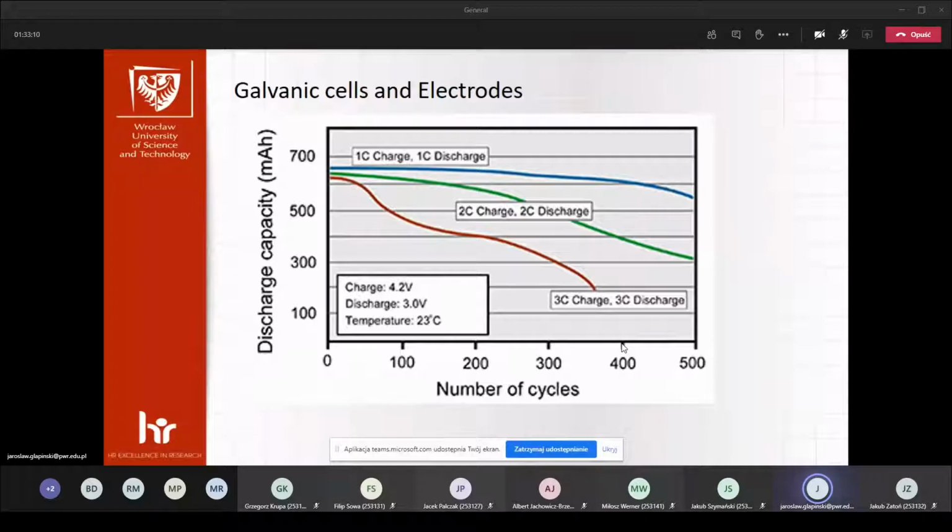So the nickel metal hydride batteries are better to use for smaller currents, because we can store the energy through more charging and discharging cycles, and use the nickel cadmium batteries for higher currents, because they are better for higher currents. Okay, so what next?